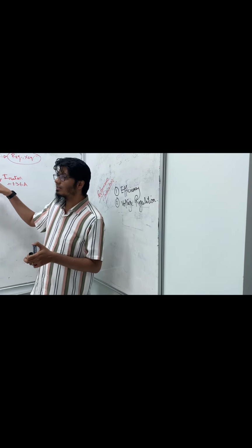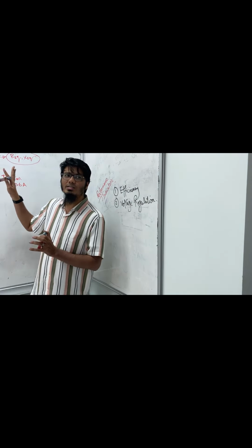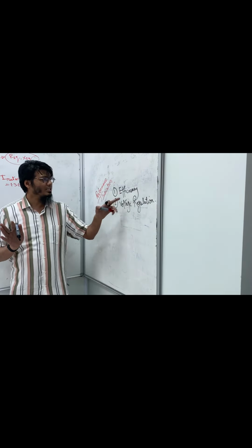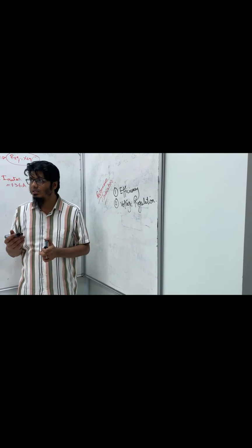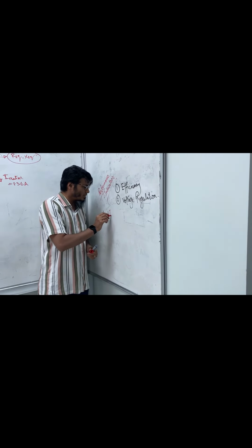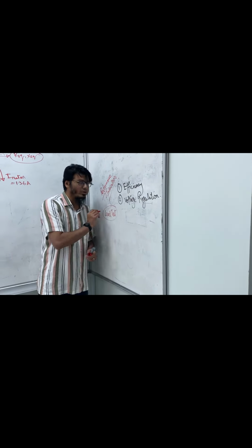In the other it is short, that means voltage is 0. So you cannot find efficiency and voltage regulation using open circuit test and short circuit test. So what test will you do? You will do another test, known as the load test. In the lab manual they call it load test.